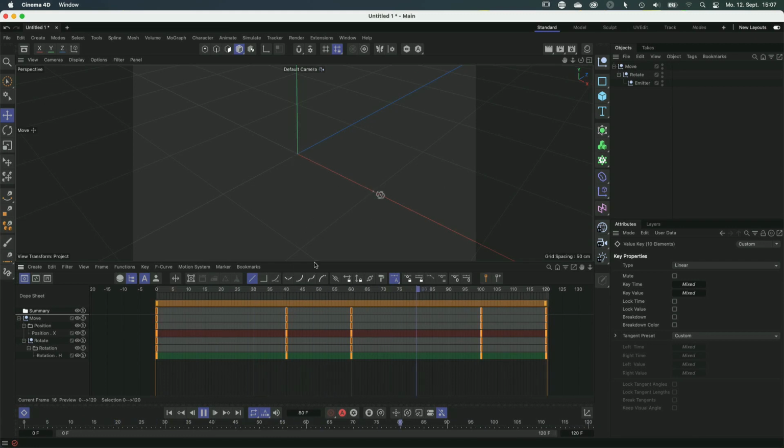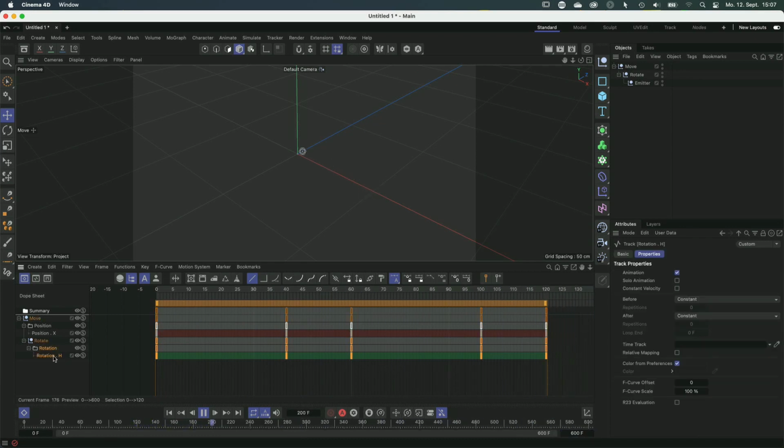And the thing that we need to do from now, if we want to make it loopable, is we just extend the timeline, and then there is a parameter when you select the track that is called After. So what am I going to do after this? You can just set this to offset repeat. I like offset repeat over repeat because it adds the offset and then repeats.